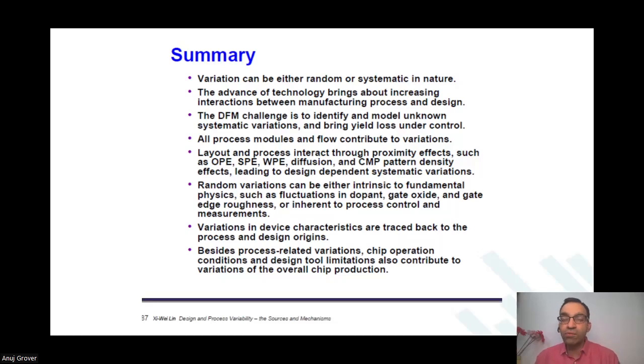So for the sense amplifier, when you design the sense amplifier, you will not use minimum length devices if you want to reduce the random variations. For the memory cell, we do not use the minimum length devices. Two reasons: we want to reduce the leakage, but also because the variation impact can be very, very significant if you use minimum length devices.